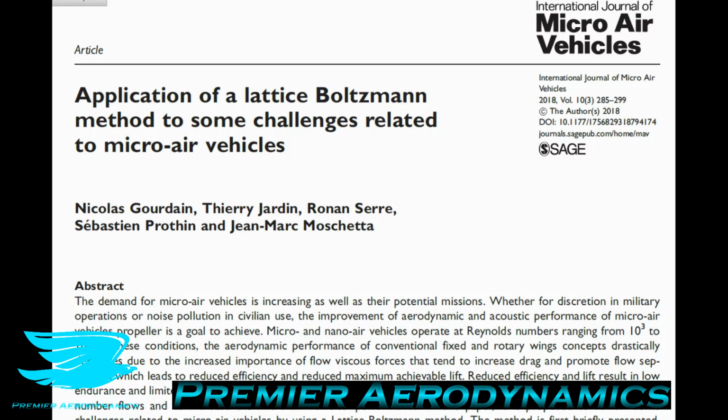So what we actually do is we get our flow again, and we split it up linearly, effectively. We'll get into a little bit more about this later. I'm just giving you a general idea. So let's say you have a flow which is 1 meter long, and you want to split it up into 10 points. So each point is going to be 0.11 meters spaced. So 1 divided by 9, plus 1 cell or 1 point at the start. So that means 0.11 meters, so 11 centimeters.